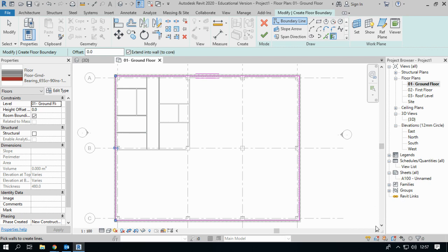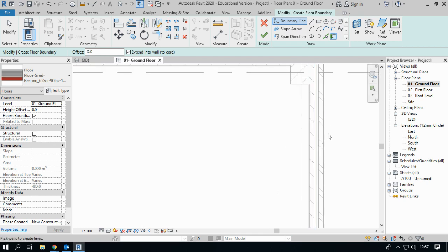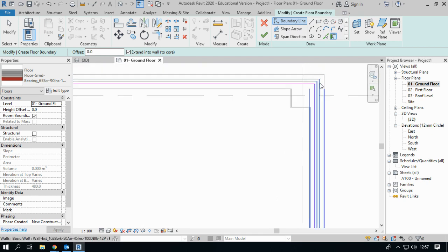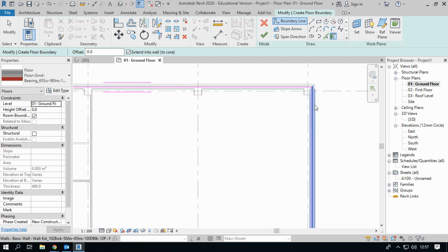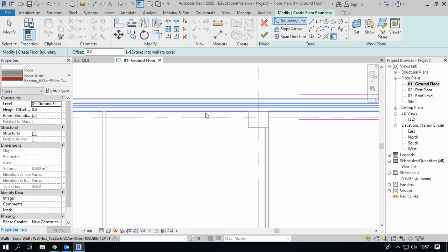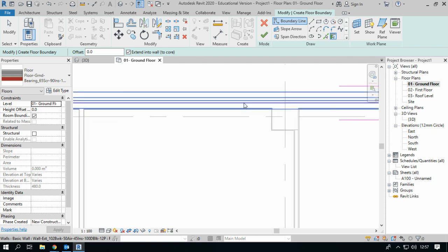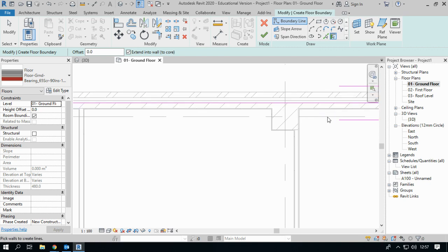It will show you where the gaps are and what errors there are. That's why the Pick Walls tool comes in handy, because it's more accurate and there's less likelihood of you not making a clean line. You can also see here that the line has been put into the wall, at the external surface of the core of that wall. So it will sit on the blockwork by itself.